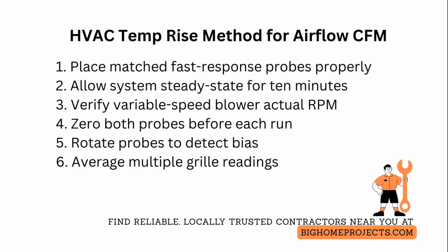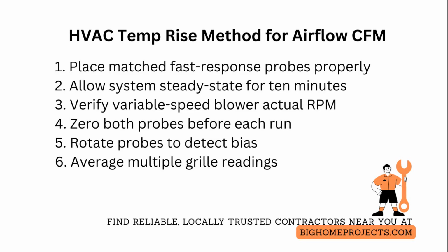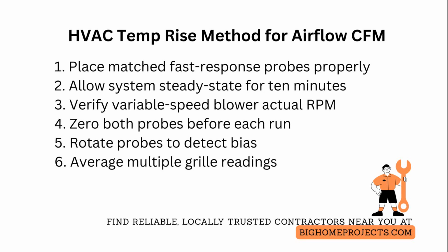Measure supply and return temperatures with two matched, fast response probes placed close to the airstream without touching metal. Calculate temperature rise as supply minus return, then apply the formula. Airflow CFM equals heat input in British thermal units per hour, divided by 120 times temperature rise in degrees Fahrenheit.